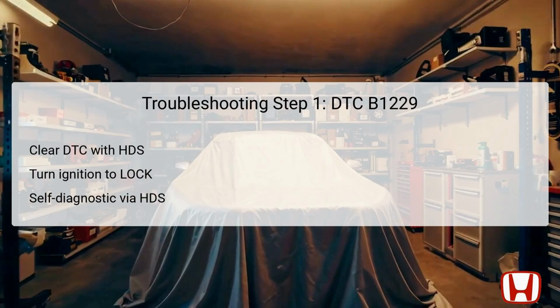After completing the self-diagnostic, you must check the system for any return DTCs. If DTC B1229 reappears, this indicates a persistent issue that requires further investigation. However, if the code does not return, it may suggest an intermittent failure, prompting the need to check for loose wires or poor connections in the sunlight sensor circuit.